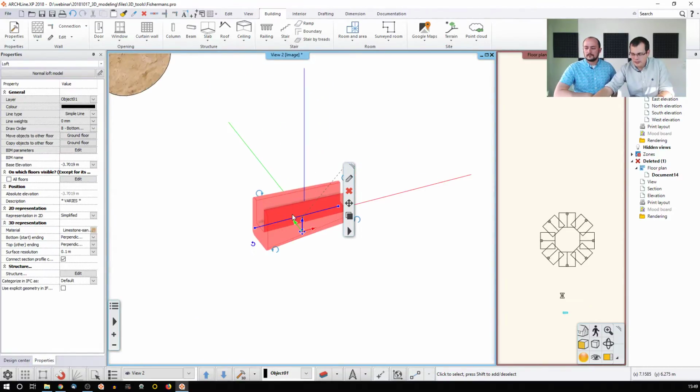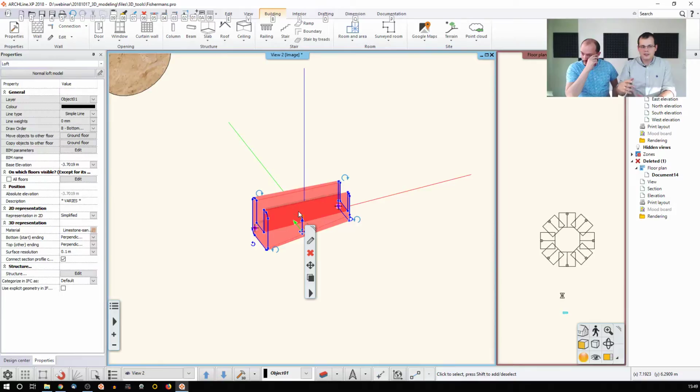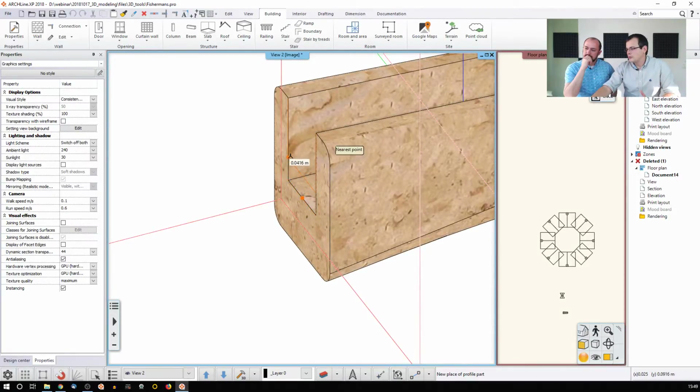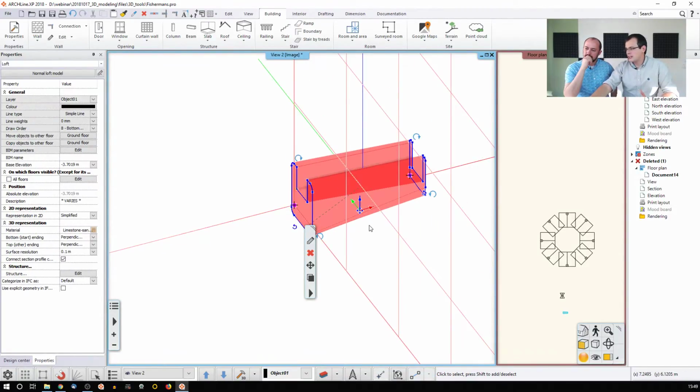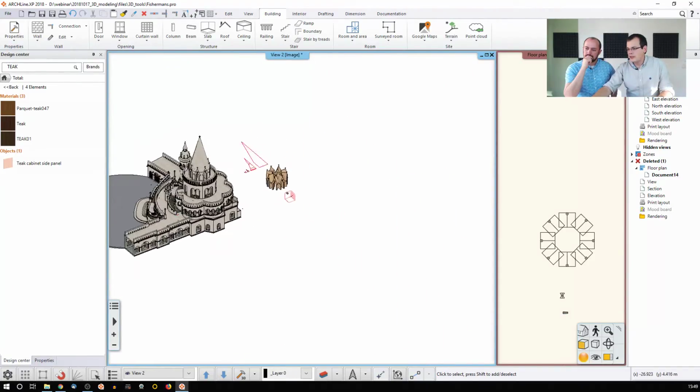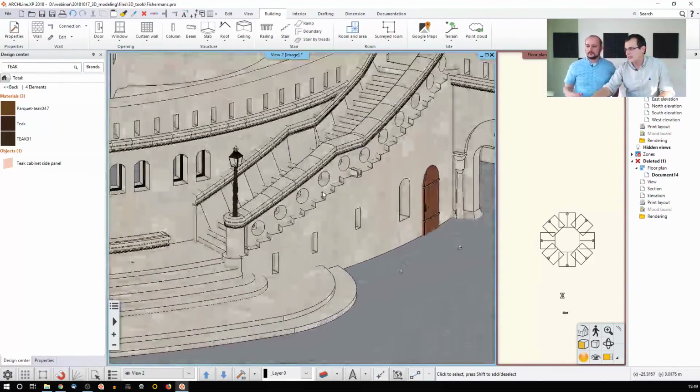So if I hit the Alt key and I click any kind of things that you have created with the loft, you see the cross sections here. You can redesign it, so you would be able to change them. Obviously, this is not going to do too much good to my model, but that illustrates that if you have a loft tool, just hit Alt key, click on it, you enter the component mode, and then you change it the way you want.